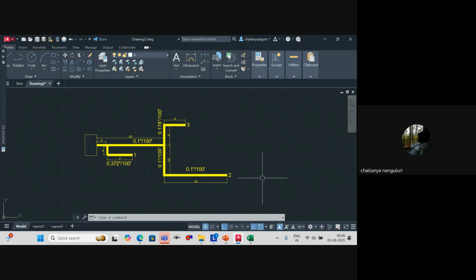We use the constant friction method or velocity reduction method. And instead of all these headaches, we'll go for volume control dampers where we apply manual resistance to make sure that the required airflow rate is achieved. So we'll do air balancing once after the job execution. Understood or not? When you do the static regain method, you need not do any air balancing or anything, but the calculation will be a headache. Instead of that, practically we always go for the normal method, where you use the velocity reduction method or constant friction method. So using these elements will basically work on your design.